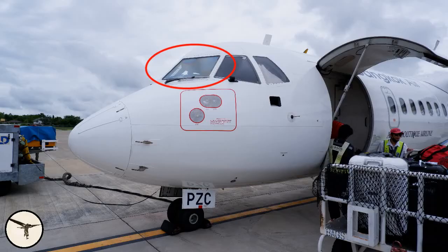The windshields have a thin film of gold embedded between 2 layers of glass. It is supplied by 200 volts AC wild electrical power. The temperature is electronically controlled. The auto temperature is plus 2 degrees or more, and the inlet temperature is plus 21 degrees or more. Normal procedure is to select the push buttons on before the first flight of the day and off after the last sector before we leave the airplane.